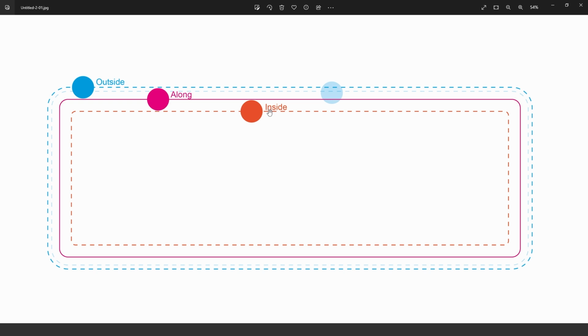And I also mentioned that allowance option. Now the allowance only applies to inside or outside, and it is about offsetting the actual line itself. So we just said the bit is 6mm in diameter, and therefore the actual path it will follow will be 3mm away from the drawing we have done. Now we can use the allowance to bring this in or out if we want to give ourselves a little bit of a gap. Let's say, for example, we are fitting two parts together. If we cut one exactly on the outside and we cut one exactly on the inside, the two parts would be extremely tight being pushed together.